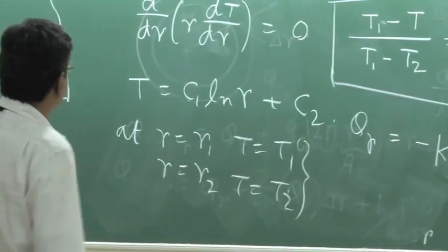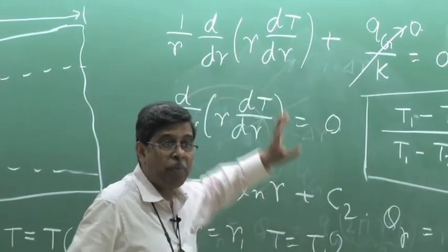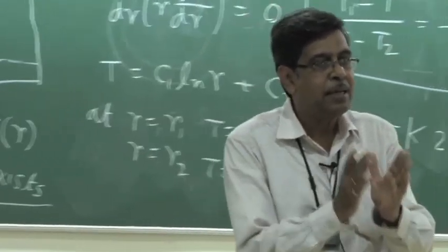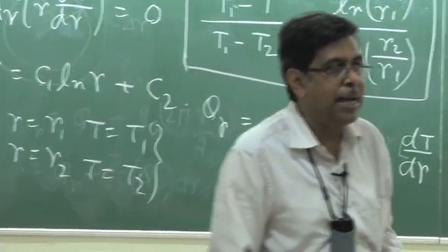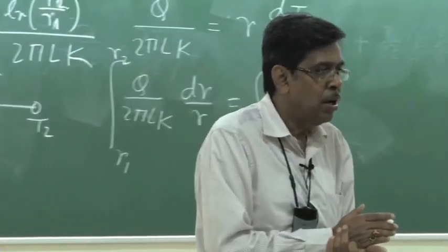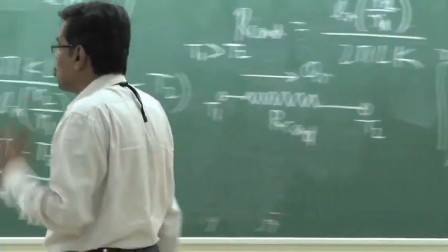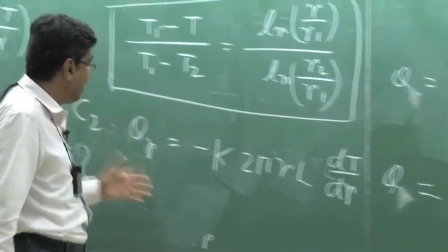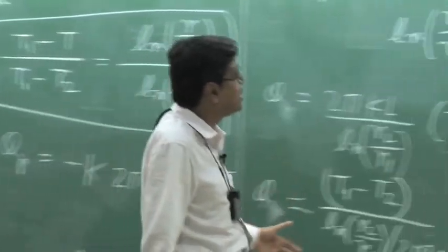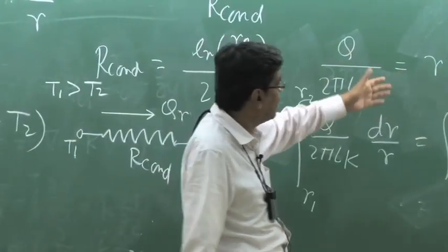But it is always better to derive an equation, because under certain special or complicated cases you must have the practice of generating the basic equations from an energy balance over a small element of the heat conducting medium. This is always good, so that you arrive at and solve the temperature distribution and then write the Fourier heat conduction equation. And this is one of the easiest ways most books write it: taking Q to be constant across all sections, you get this.